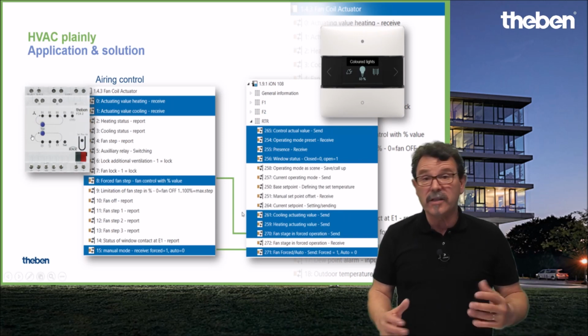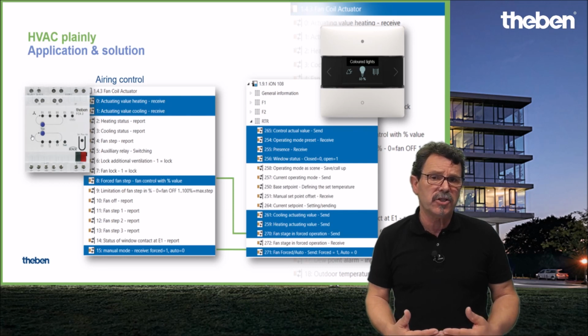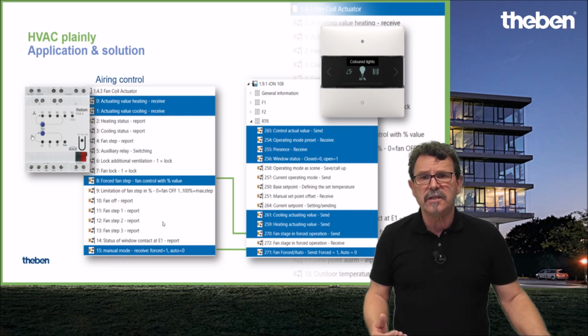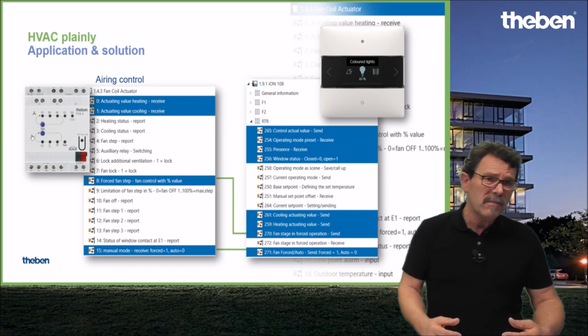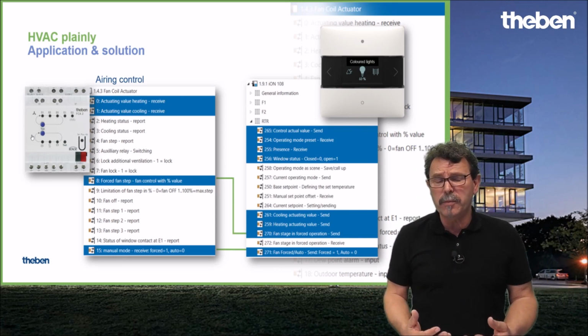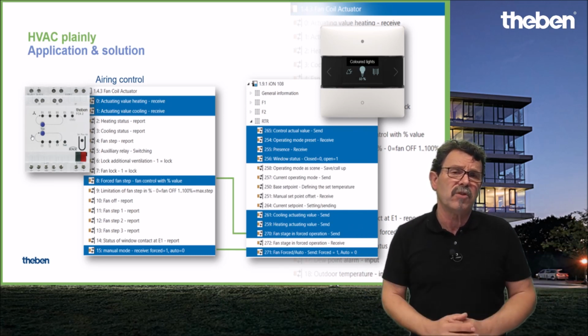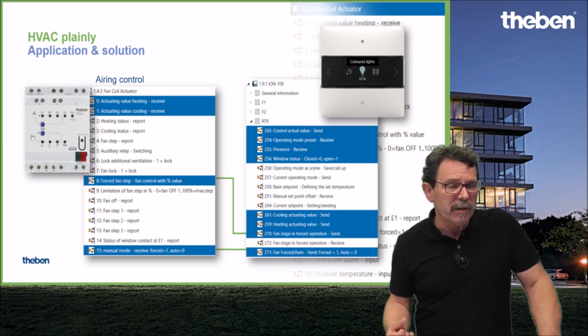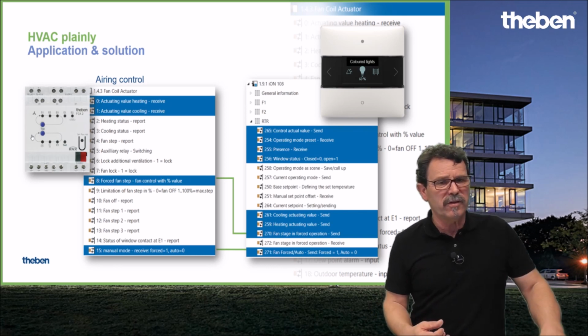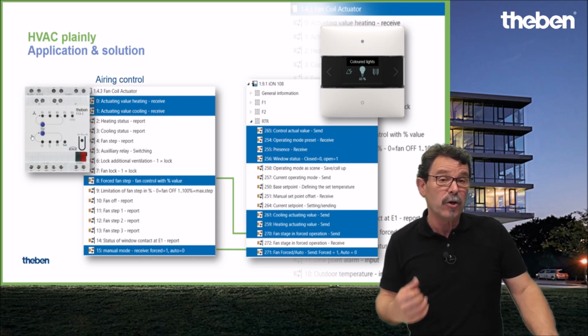When it comes to the ventilation, in this case I set, for instance, ventilation as a value. So then you have just to link these two communication objects. You need just this fan speed or the fan forced mode. This is highly recommended, especially when, for instance, you have a meeting or such. Yeah. And you know, if you have a gathering in the room and there are a lot of people inside, then the CO2 value is rising, increasing tremendously. After half an hour, easily, you will have values which are definitively above the desired values, let's say it this way. Yeah. So that means we need this airing, but probably during the conference, it is not that comfortable to have these noisy wind streams or probably an audible noise from the fan.